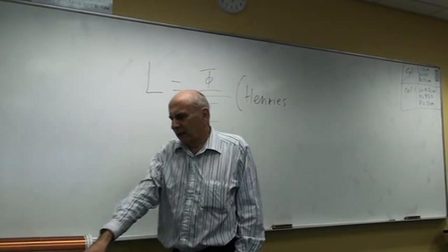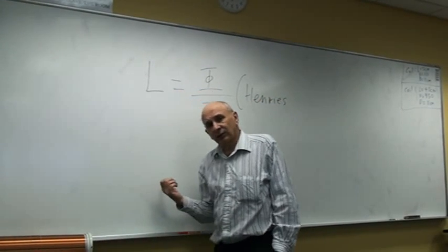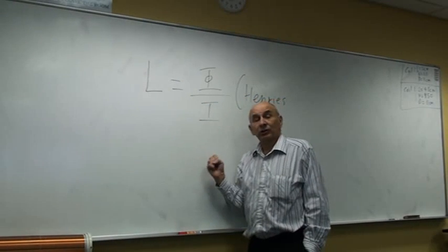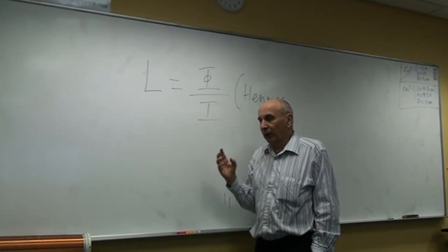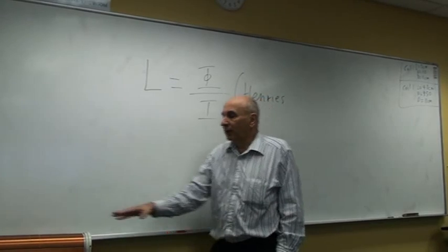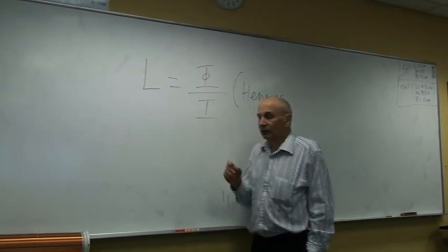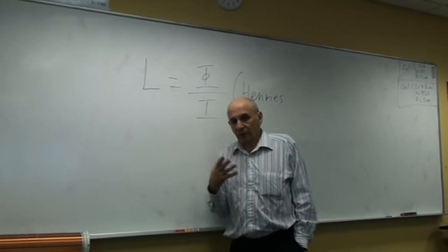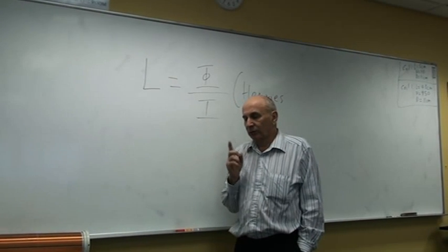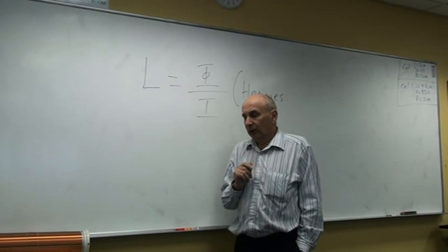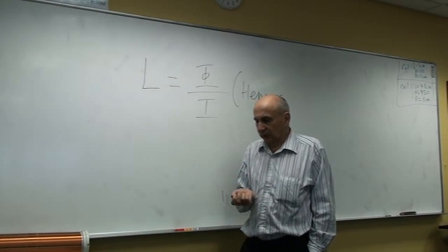Next thing it says, if the frequency changes, does the inductance change? And the answer to that question is no. Inductance depends upon purely the dimensions of the coil. It does not depend upon the level of current or the flux flowing in the coil. So the answer to question 2 is no. Inductance does not change with frequency.